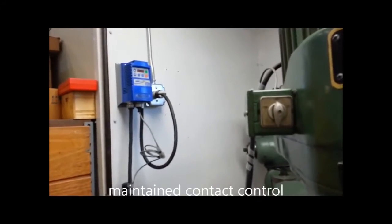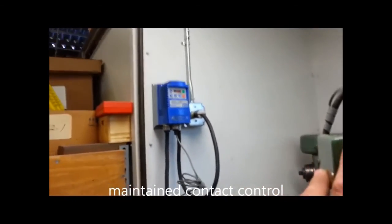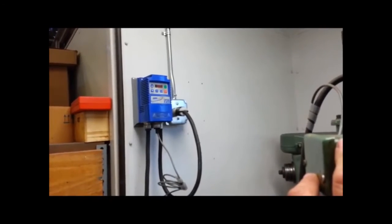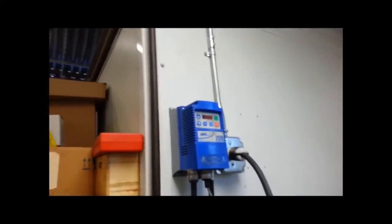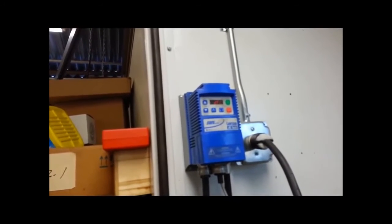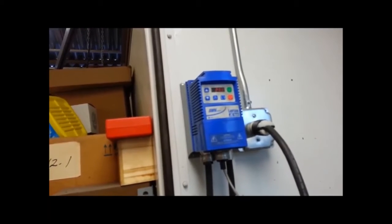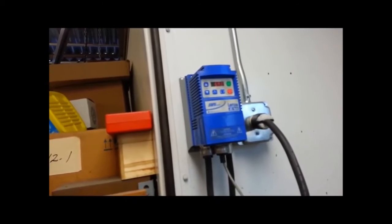Let me talk about the different ways to control. This is set up to remote start and stop. I turn on my switch here. As you can see, I'm ramping up over there. And now we just hit 60 hertz. Here, if I can zoom in just a little bit on that thing. Okay, then we ramp back up to 60 in the forward position. I'm in the forward run position, and now you're running at 60 hertz.